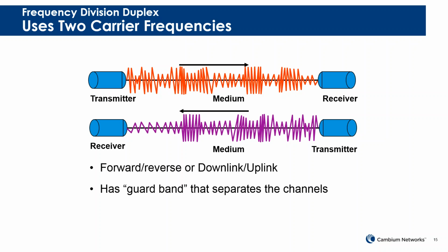Pretty much, yes. When you're dealing with these frequency division duplex type of technologies, usually these frequencies are close enough to each other that the same antenna can be utilized. It's not like one transmitter is using 900 megahertz and the other transmitter is using 5 gig, where those types of antennas are dramatically different in design, and you couldn't design an antenna that could do those two different frequencies in the same thing.